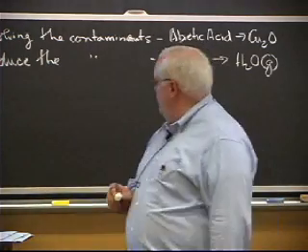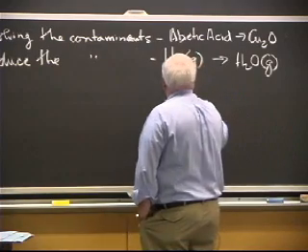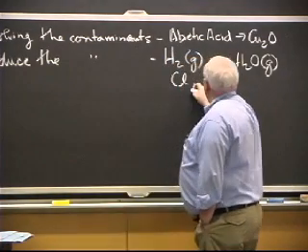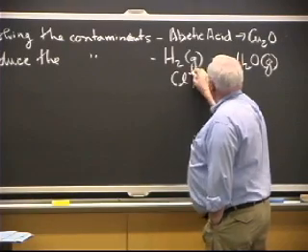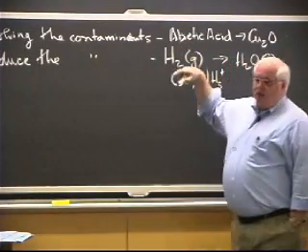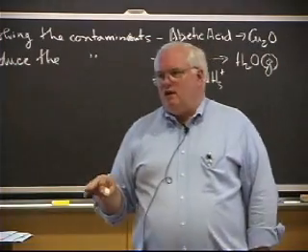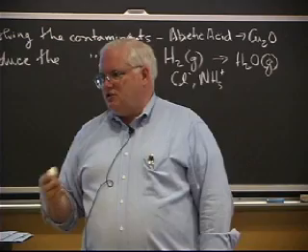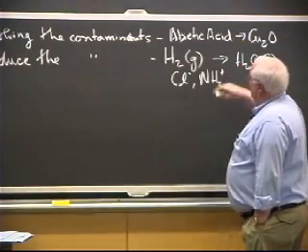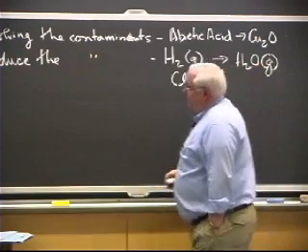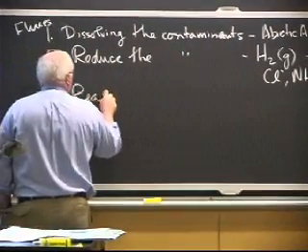In terms of reducing things, another example is to use chlorides, or amines in soldering. And that's what happens when you add a little bit of hydrochloric acid to that acetic acid. You now are getting something that eats away the copper oxide as well as it dissolves it, changes it to copper chloride. And the copper chloride is more readily dissolvable in the acetic acid, so it cleans it quite well. And the third thing, unfortunately, is called a reaction flux.